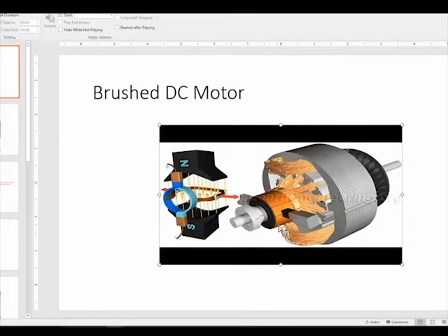So I'm going to pause there for a second. And so with this discussion in mind, I'm going to pass around both of these motors in case you were not able to see this on Monday. Try and map what you see here to this video and also our discussions. Some of the elements that you'll see, you can see in both pretty well. These commutator rings, which is where my cursor is right here, or commutators, are also sometimes called brushes in what you call a brushed DC motor. These are these elements right here. These are these green things on this motor, and then they're copper colored on this one.